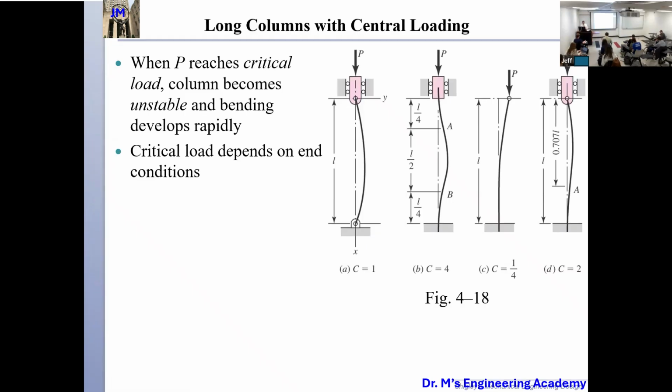So this is buckling, and we have four key scenarios. The first one is the two ends, and they are pinned. Pinned means the translation is fixed: it cannot translate in this direction, nor in this direction. But it can rotate, so rotation is allowed here.